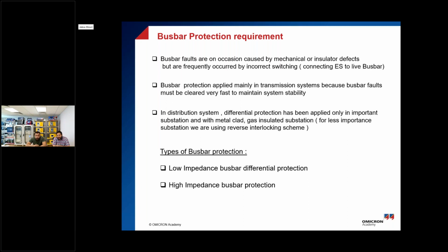And the busbar protection is mainly applied in the transmission network, and also it can be helpful for the distribution or the sub-transmission network. In the distribution, differential protection. We don't forget that it's a costly system. Yes, it's not complicated. It's basic, but it requires more experience to deal with this application.